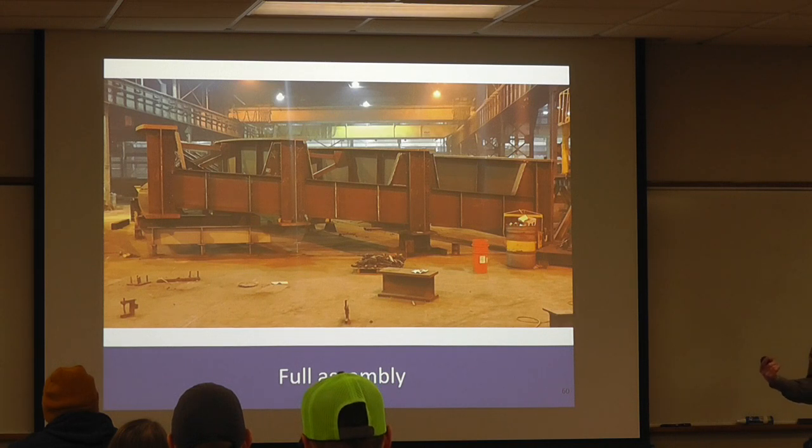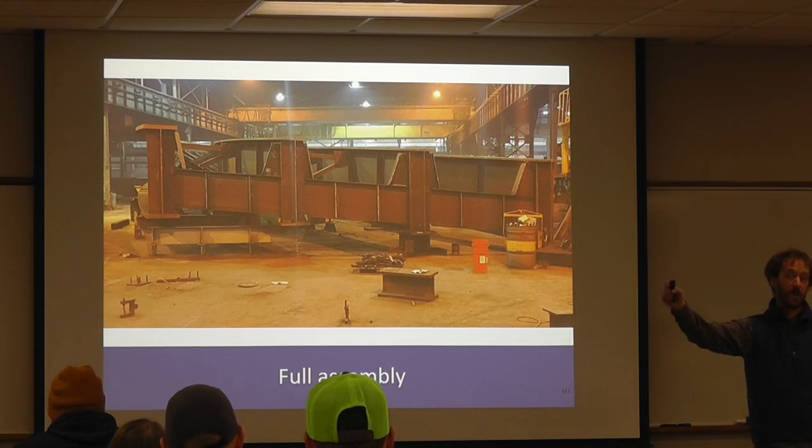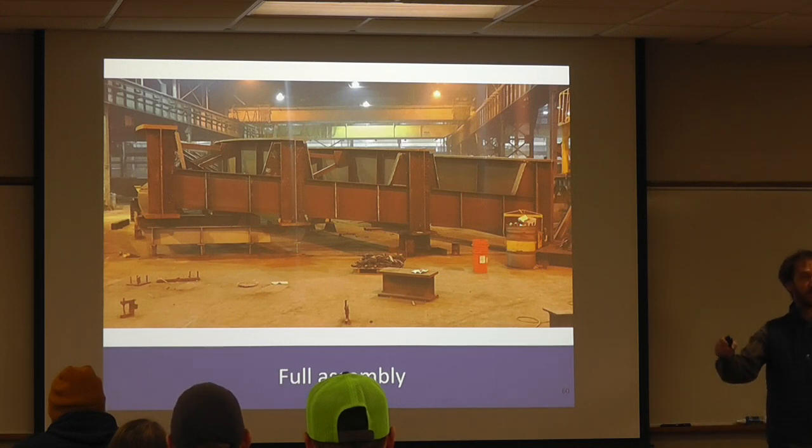Does that make sense? So these are generally a bit more challenging to erect because that piece has to be installed in that location. And here, fabricators got the opportunity to put blocking every 5 to 10 feet, right, to manipulate that shape. Think about this in the field. How often do you have a shoring tower every 5 feet? You don't, right? Usually it's, at best, 2 cranes and maybe a shoring tower. Sometimes it's just 1.